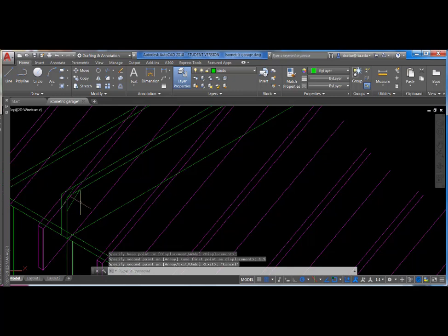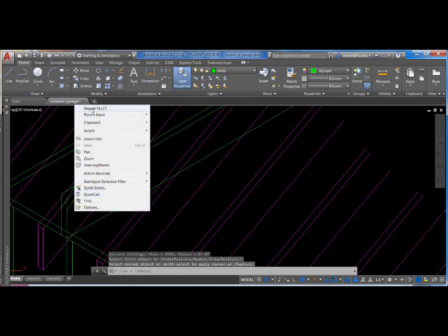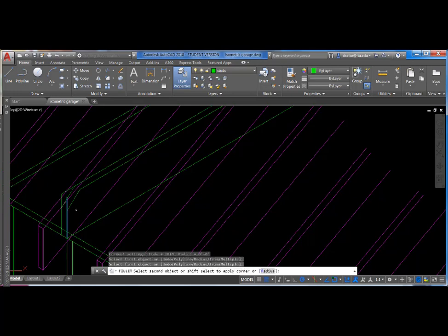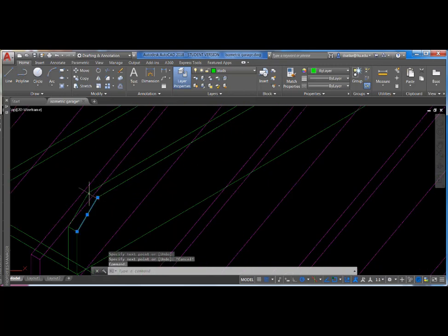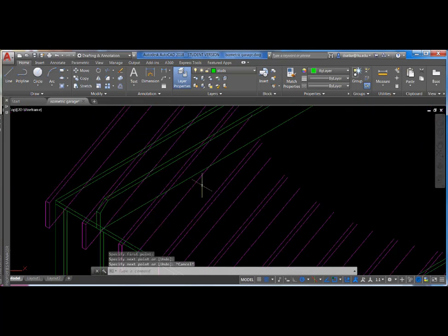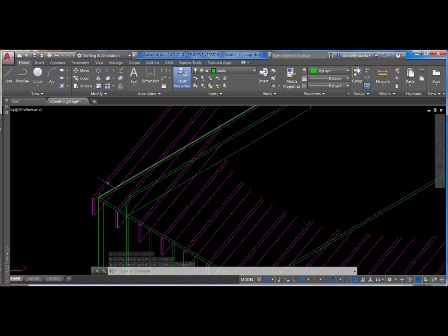so we can go ahead and fillet this. Fillet this, and it gives me my typical joist. A couple more lines here. Two lines here, and what they're showing is that this little corner has been cut off, so the joist can sit in there nicely right next to the roof rafter.